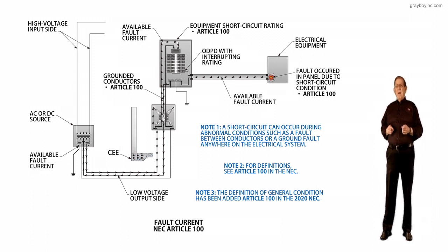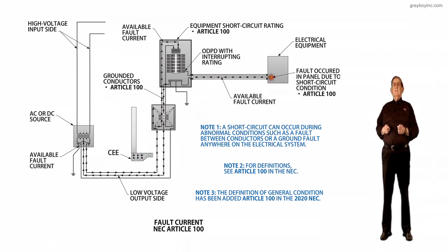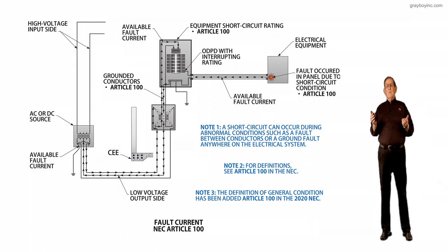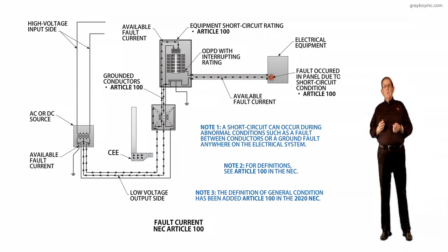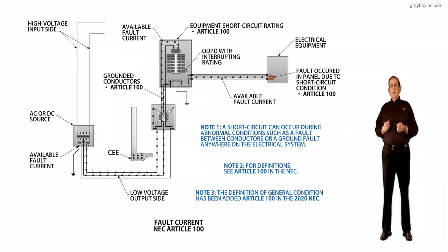And notice maximum was deleted in the illustration because this section, the utilities just couldn't give you the exact fault current due to transformer taps being made on their lines, big motors starting, large motors, high efficiency motors starting with higher inrush current. So they just kind of gave you under normal operating conditions.